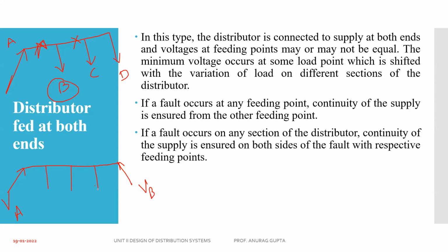It's a very good point for all of you. Now again we have some points called C, D, E. If voltage comes at this point, C, D, E, all three consumers are still getting some power from this end. If voltage comes from here, then at this time C is getting power from A, clear, while D and E are getting power from B.